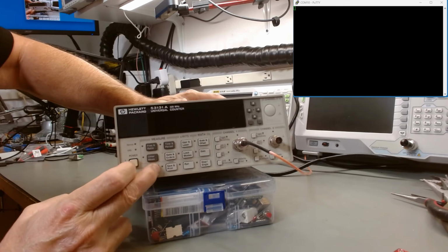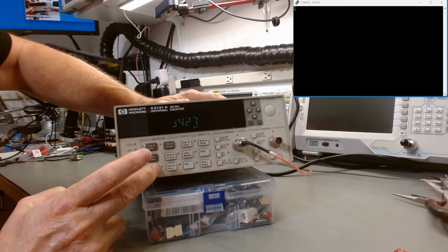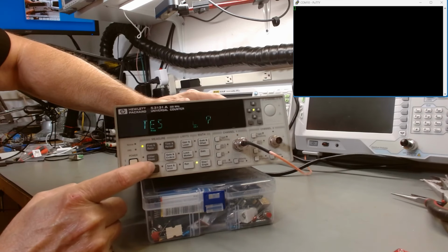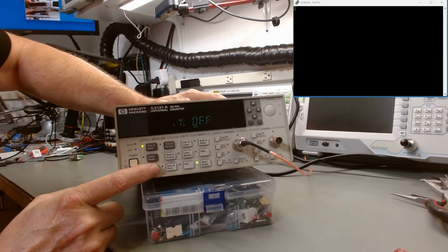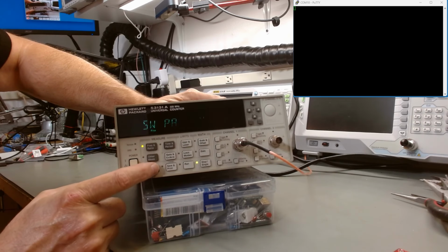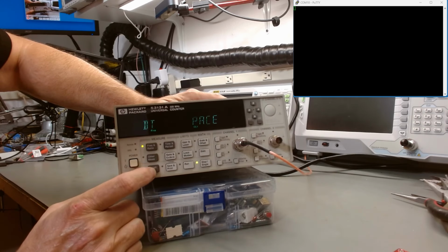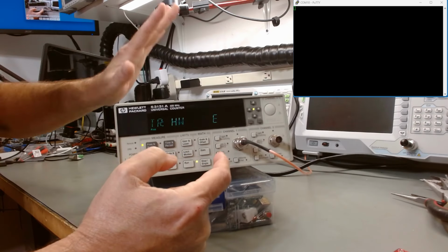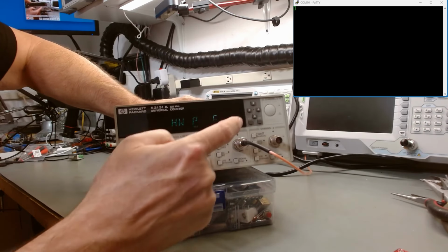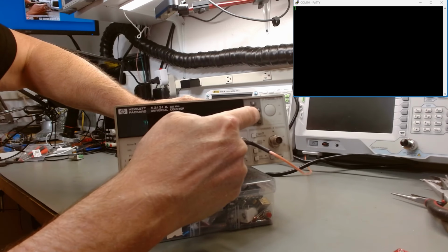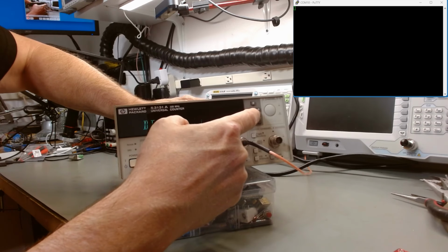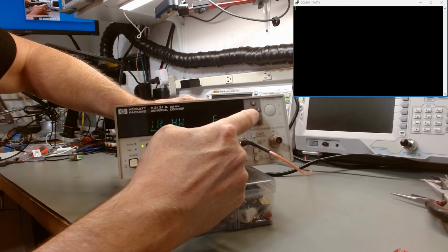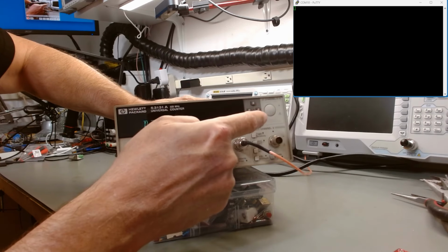Let's turn the meter off, hold recall, hit power, and go to the COM port settings. Okay, 9600, yes. Parity off. Software pace, none, correct. This one bugs me: hardware pace. Well, we're not using hardware at all, so I'm not sure why they said that should be on. I know I don't want limit; it has to do with setting upper and lower limits. And the other choice is high. So how about we do this?